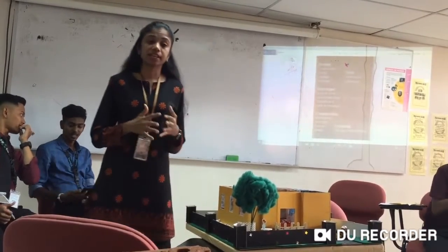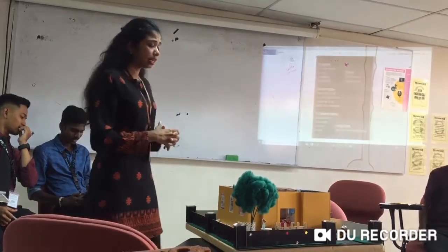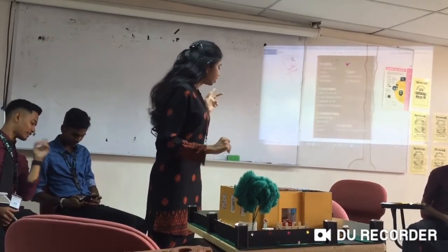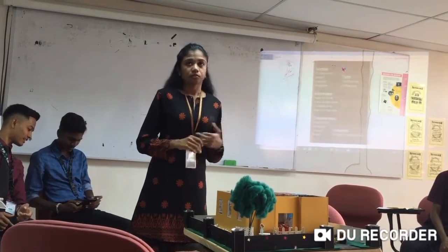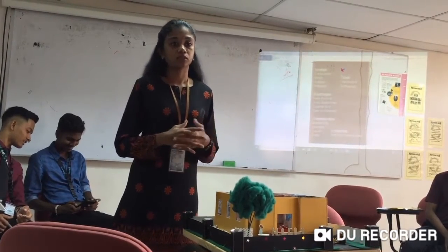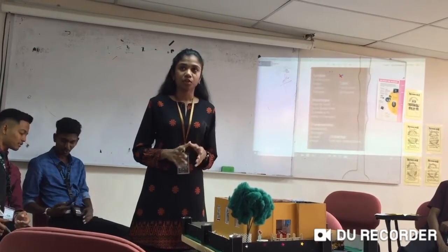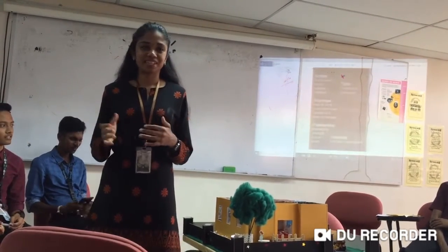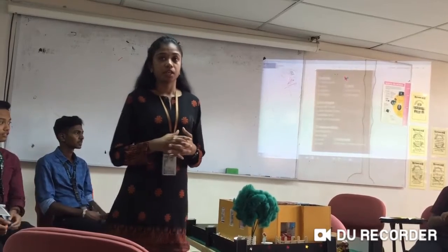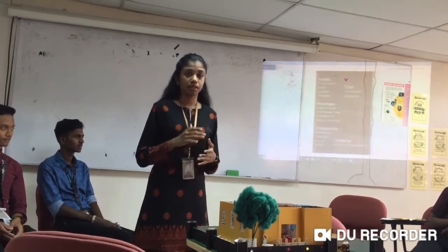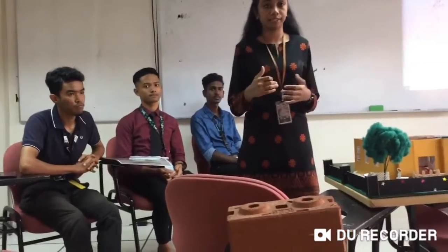Okay, let's see what the characteristics of timber are. Here I come with 4 characteristics: workability, strength, smell and also color. Workability is the ease with which timber can be cut into the required shape. Timber is usually very easily workable. It should not give any damage or block the teeth of the saw during cutting.